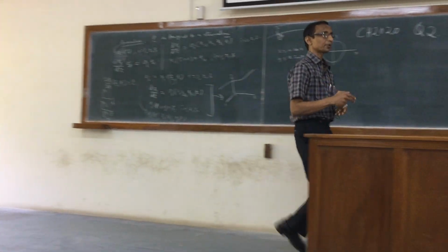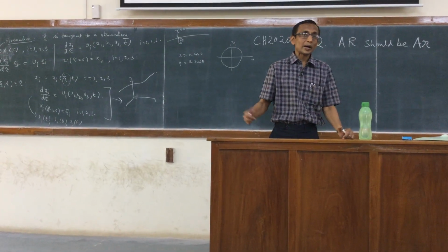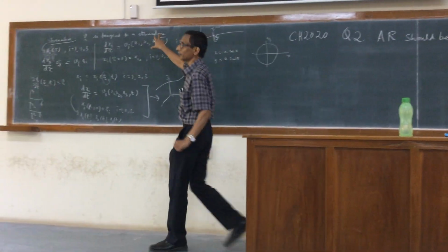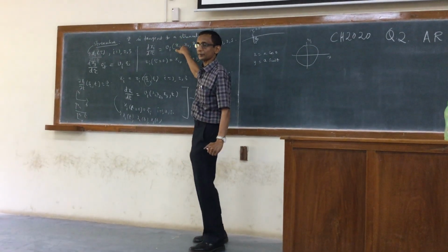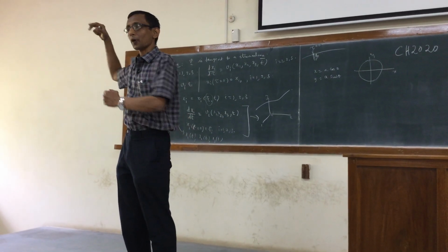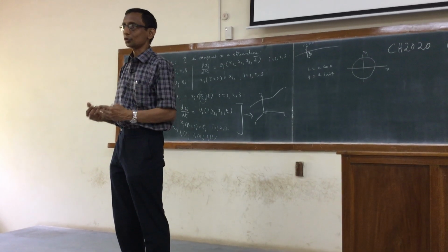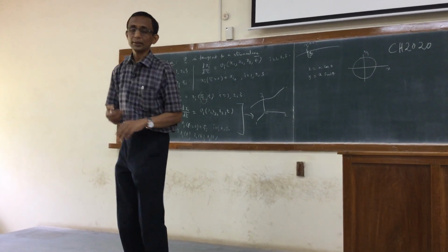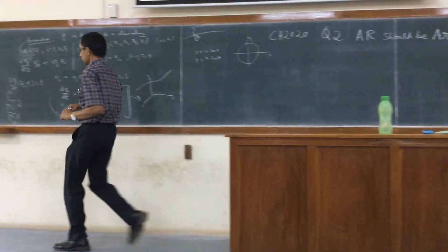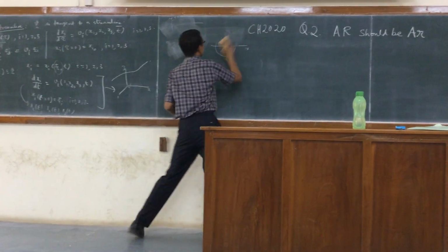So this is how the streamline is. Not streamline, the particle path is constructed. So the time is very much there. For streamlines you freeze the motion in time. Here we are following the motion of the particle with time and then plot it in space. We get the particle path, but there is no reason to require that the two will be the same. Right? Now Aris has given a couple of examples. We take one of them. He says that the two will be the same when you have steady flow.